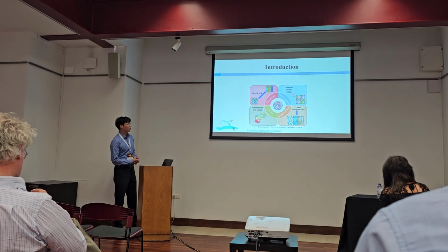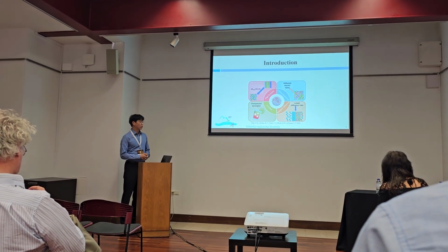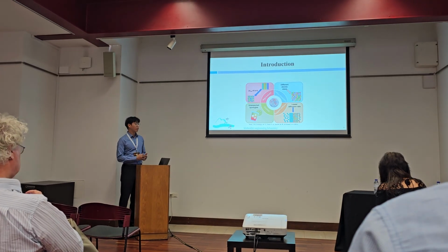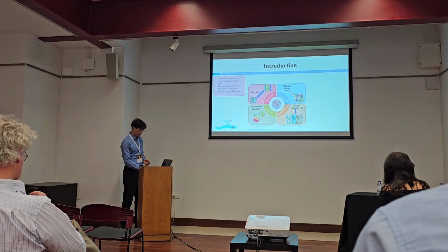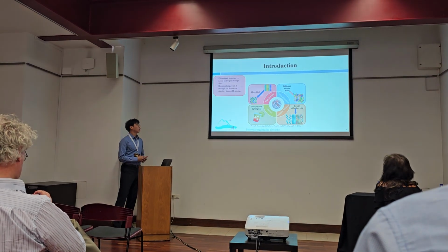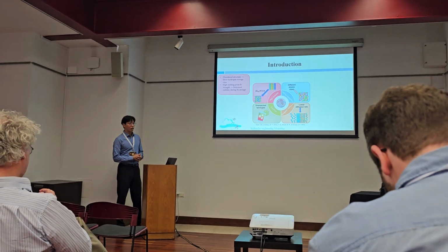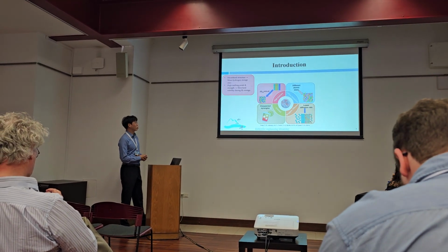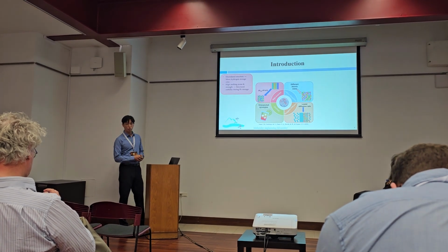This is the reason why we choose high entropy alloy. High entropy alloy has four effects and is very excellent for hydrogen storage. First is the high entropy effect. Their disordered structure provides more hydrogen storage sites, and a high melting point and stress make structural stability during hydrogen storage.